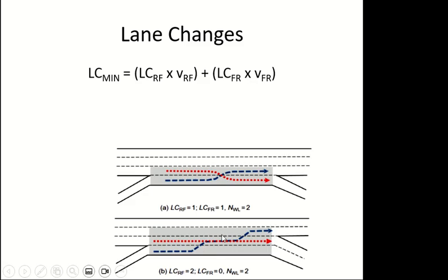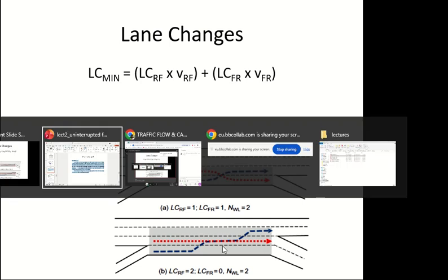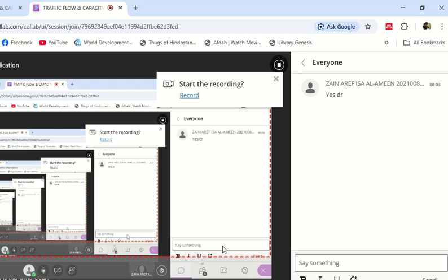Okay, so weaving lanes are these two. The top shaded lanes are weaving lanes. The bottom one requires 2 lane changes to go to the freeway. So I will put lane changes ramp to freeway as 2 here, but the number of weaving lanes will remain these 2 only, not this third one. So is this clear? Does anybody have any questions?